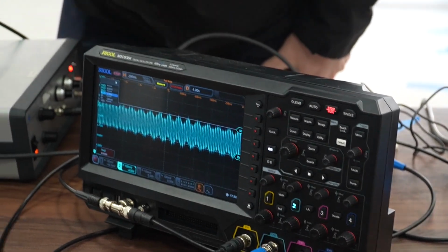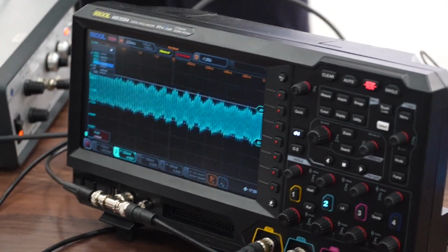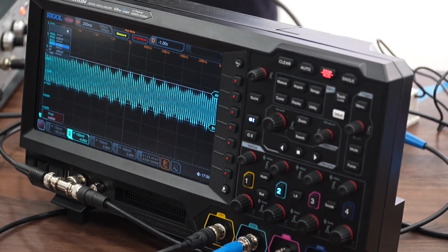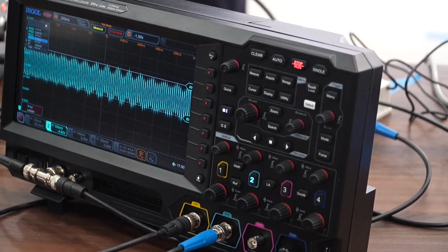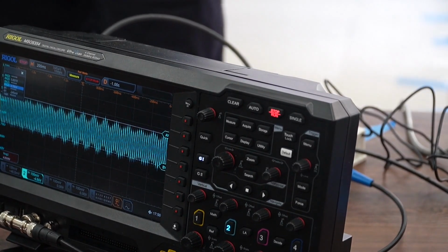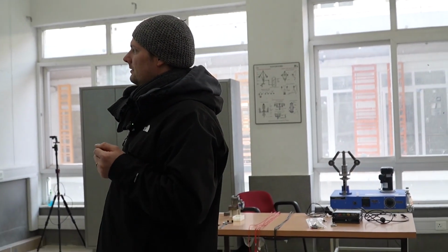The difference is 245 millivolts, right? And this is 2 times the tip deflection. So if you divide that by half, you've got the tip deflection, right? So 122.5. 122.5 millivolt. Yeah. Exactly. And then you have to write volt in there. So it's 0.1225.